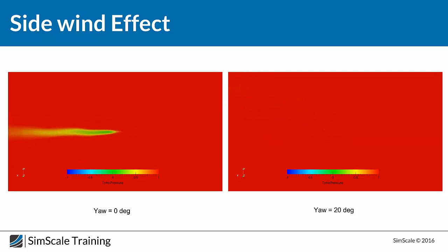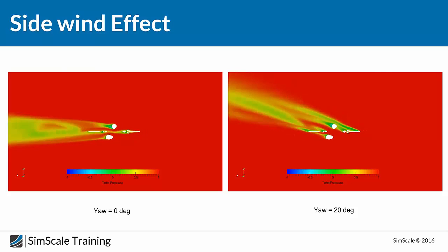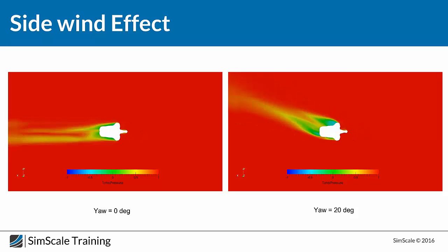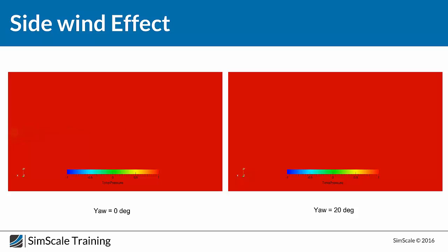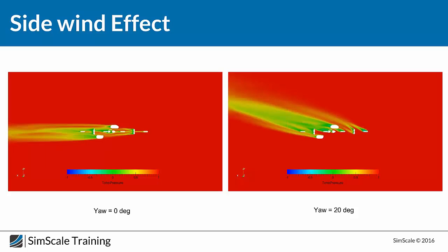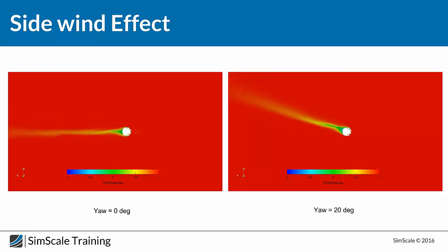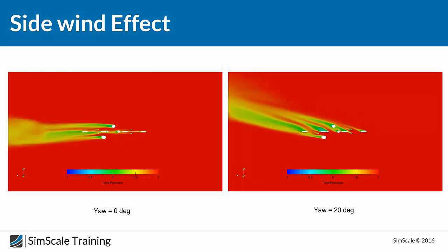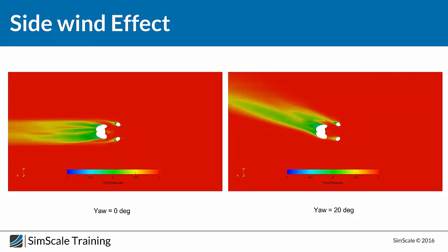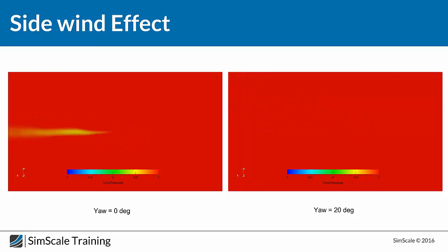Oh, okay. So instead of using the pressure as a physical quantity, usually when we compare different designs, we usually use dimensionless values, and the pressure coefficient is the dimensionless value of the pressure. So usually it's between 1 and -1.